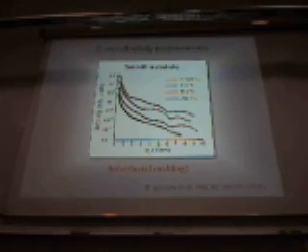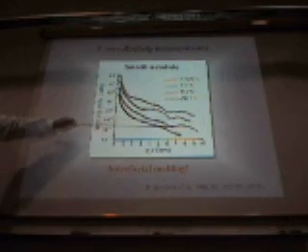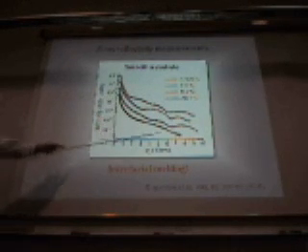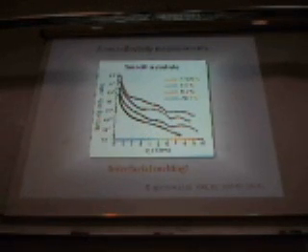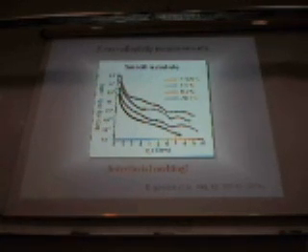Well, and this is about the only curve which is published. What we find is this: if you start at low temperature, around -25, there is not much structure on this curve. It pretty much decays like a Fresnel curve. There's only a slight bump in here, and we know where this bump comes from. That comes from the density change in the silicon dioxide. There's this native amorphous layer of around 2 nanometers there, which is producing this bump. This bump is only very slight because the density change between silicon and silicon dioxide is very small.